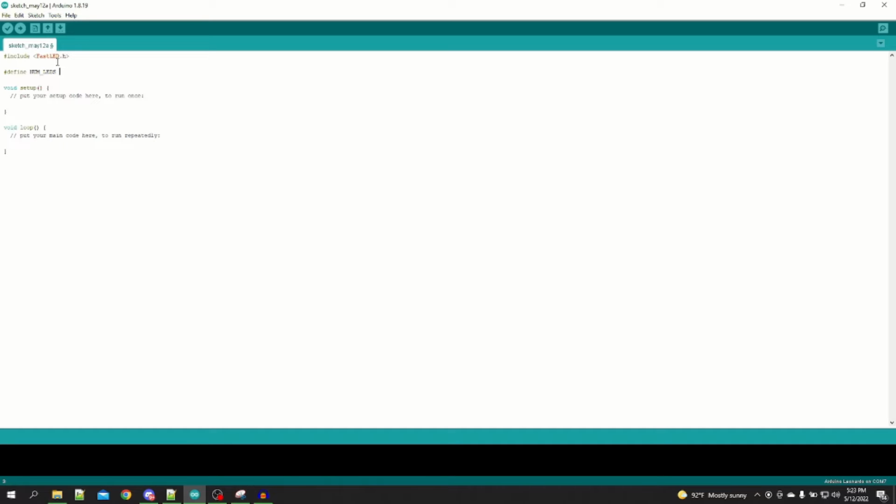So one thing I do know is the number of LEDs, that's what this one is for, on our LED string is 52. So that's what we're going to put there. And then we're going to do our next one, and that is going to be data pin. And we know that we're going to be using data pin number 9.